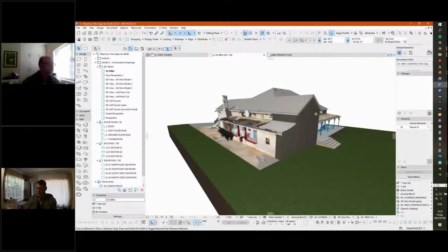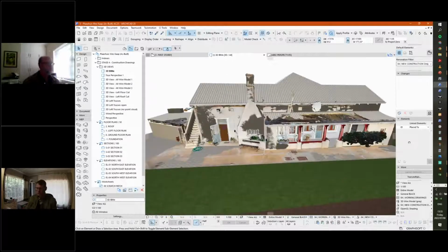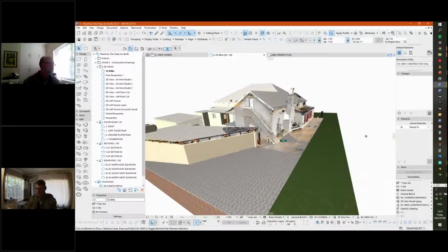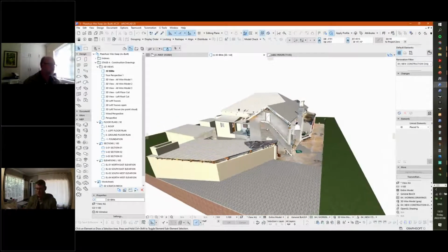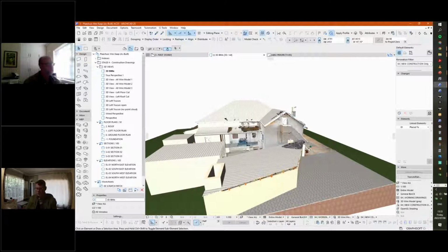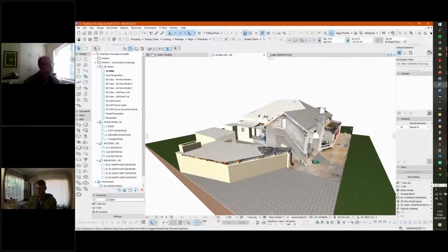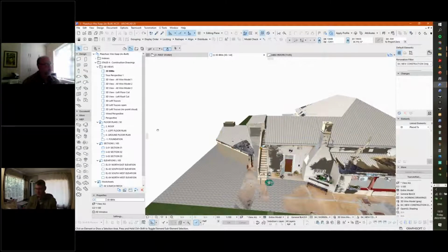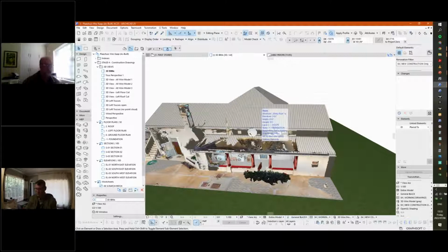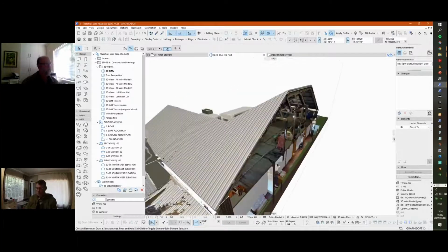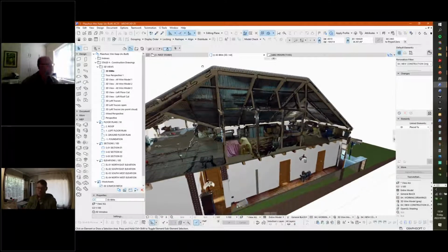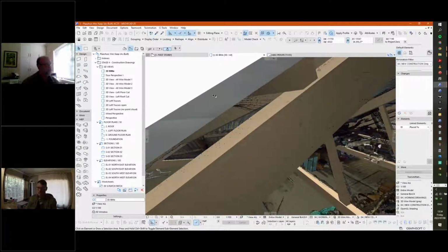It's not a very big house, but it has these outbuildings. It's already got the staircase going up to the loft. Mostly in these old places, the loft space was used for storage and is now being converted. If you're measuring this property inside and out, in the roof space, all the rooms, it's going to take you a very long time, and you might need to go back several times and not even finish in one day. All this data is captured by means of a point cloud. So the point cloud is obviously way more efficient than measuring by hand, even if you are using a laser disto.